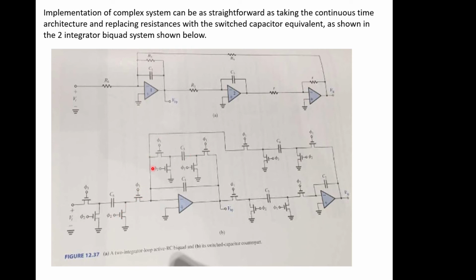And you can see the block here is all plugged in, and the block here for another resistor. So all these resistors have just been replaced. And the nice thing about this is they're all being driven by the same clocks. You have one oscillator generating the clock phases, so the out of phase clock phases, and you just feed them to the right inputs on these transistors, and so everything is then controlled by one clock.